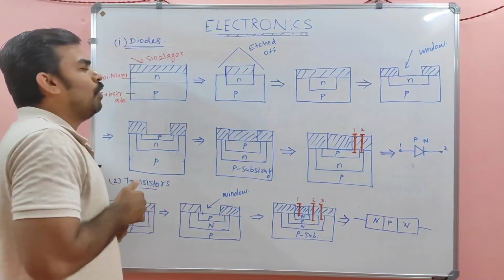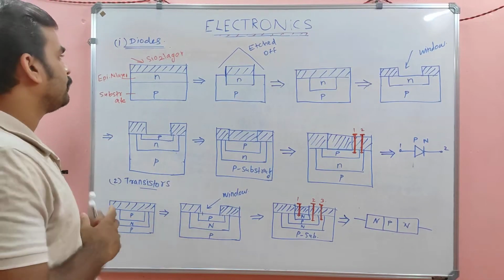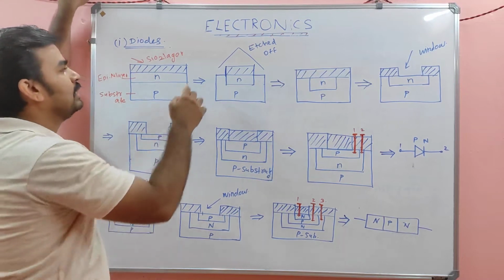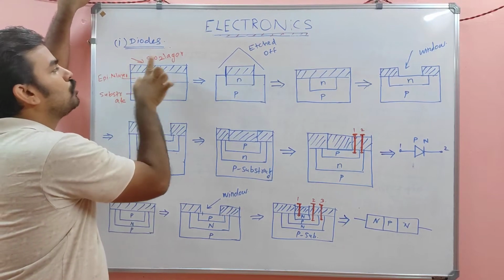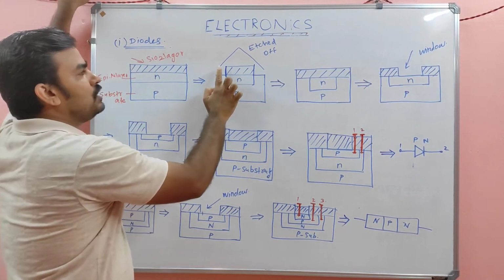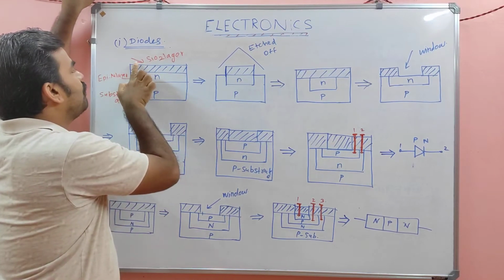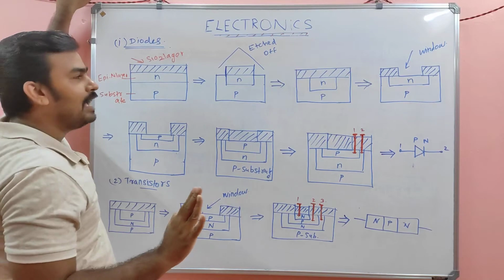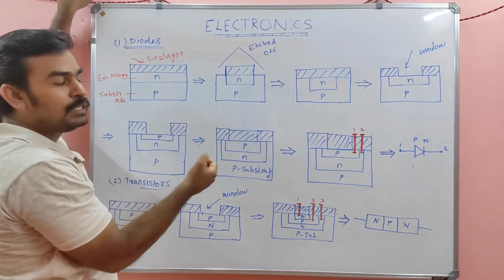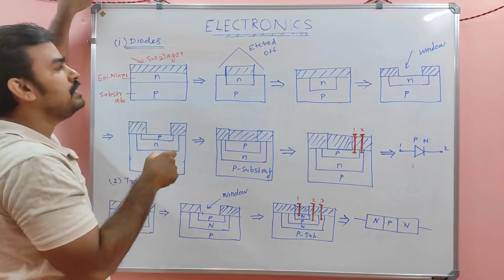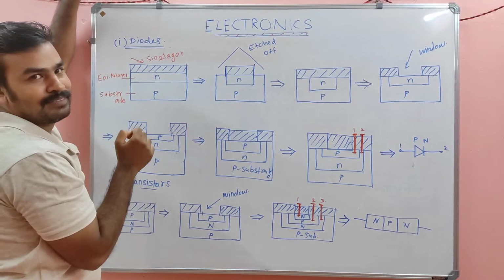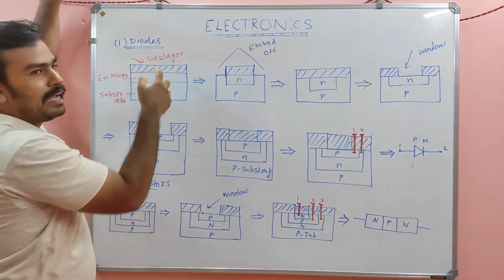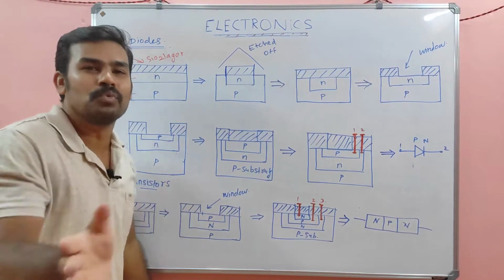Okay. So what is the next step? We have to etch the two portions, I mean the two corners. So the edge of the two corners, you have to etch here and you have to etch here. Okay, and add pentavalent impurity to the etched portion. That means if you etch the SiO2 layer, etch means nothing but simply remove.